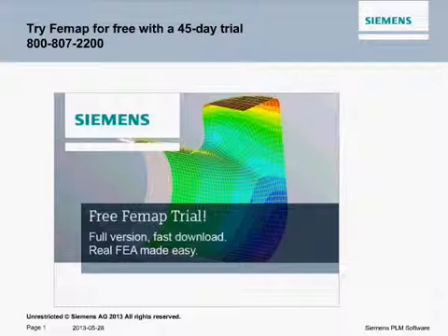I've also seen, particularly in aerospace, where they do validation. They will actually look at the FEA model and correlate the results from the FEA model to the physical test, and then tune the FEA model to match the physical test and go from there. So there's not a single answer to this. It depends on the product complexity and the use cases, and also what type of regulatory factors are involved in producing the product.